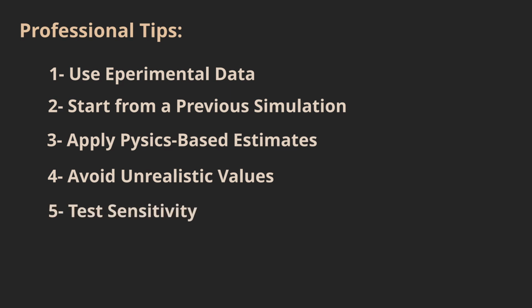Tip number 5. Test sensitivity. Finally, test how sensitive your solution is to initial conditions. And this is done by running several cases with slightly different initial values. This helps ensure that your results are robust and not extremely dependent on a specific starting point. As you see, smarter choices in initial conditions can reduce computation time, improve convergence, and lead to more accurate solutions.